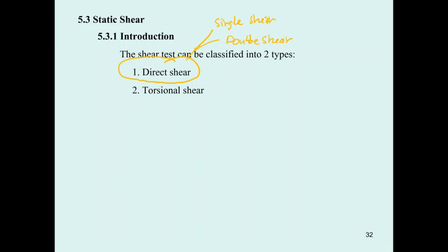In civil engineering, we also use torsion when we investigate the soil layer. We need to have an auger. The auger is a kind of shaft with a special design, so we can dig the soil. It could be a shaft like this, with some kind of spiral here. When you twist this, the auger will dig up the soil, and then you can investigate the soil layer. Also for piling, like bored piling, you bore the soil, put the reinforcement into the boring, and then put the concrete into it to produce the pile.